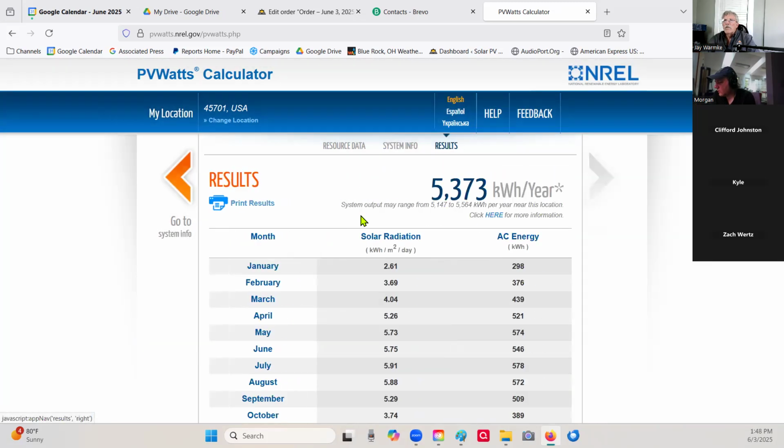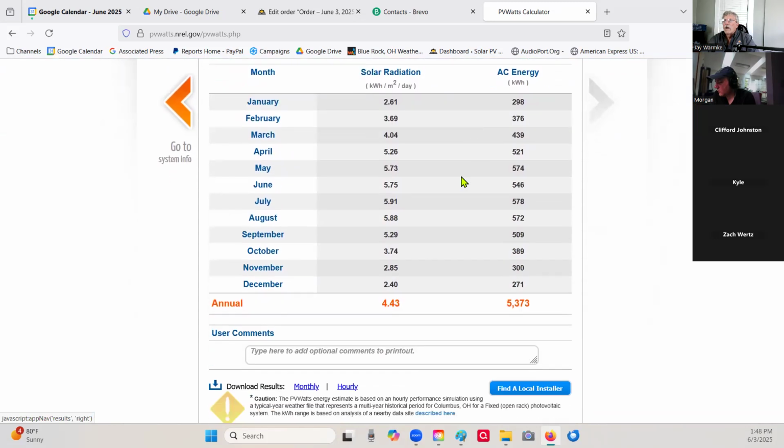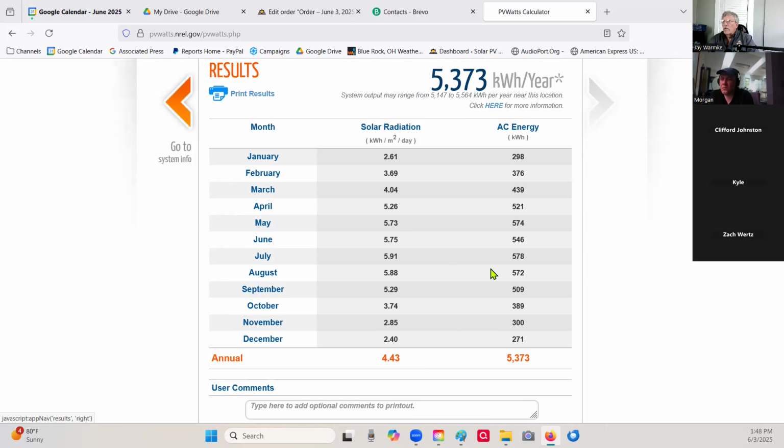And now it's saying for this location with those parameters, we're going to get 4.43 hours of insolation per day. Okay, so that varies. It varies on your location. It varies on your orientation. It varies on your D rate. But with all of the specifications we plugged into this tool, Athens, Ohio, almost south, 20 degree angle with that D rate, we're going to get 4.43 hours of insolation. Well, that comes into effect. I'll jump back into my whiteboard.